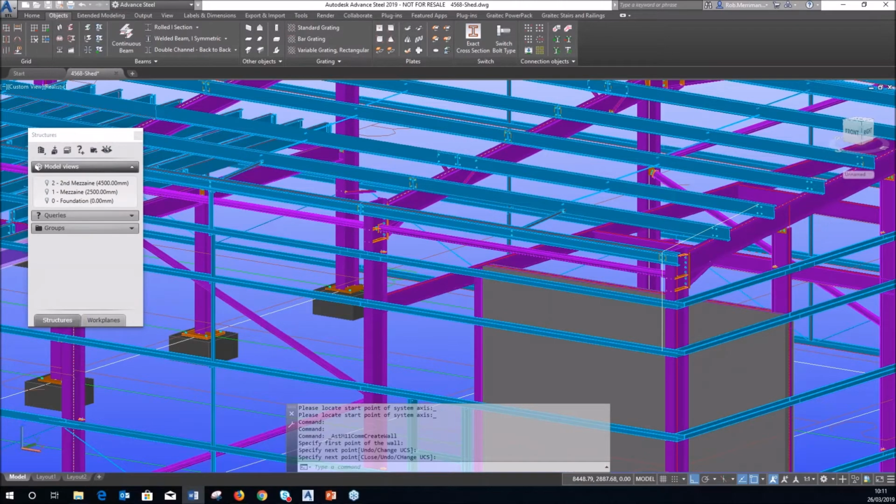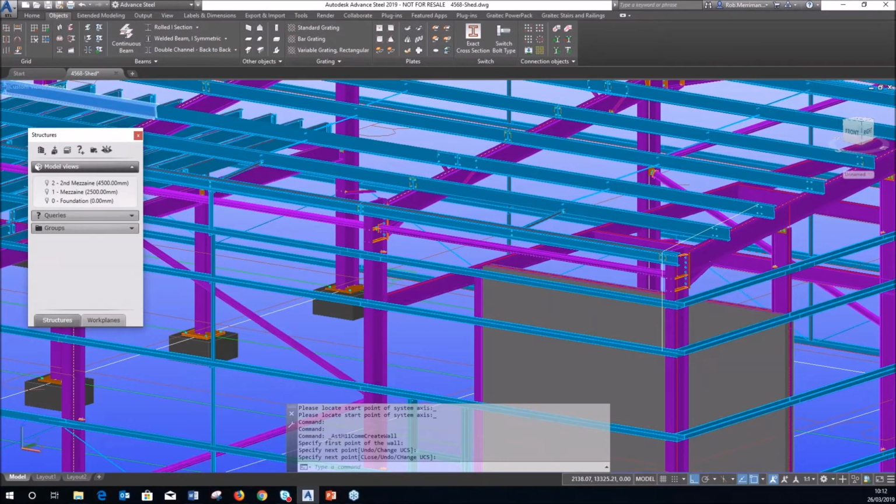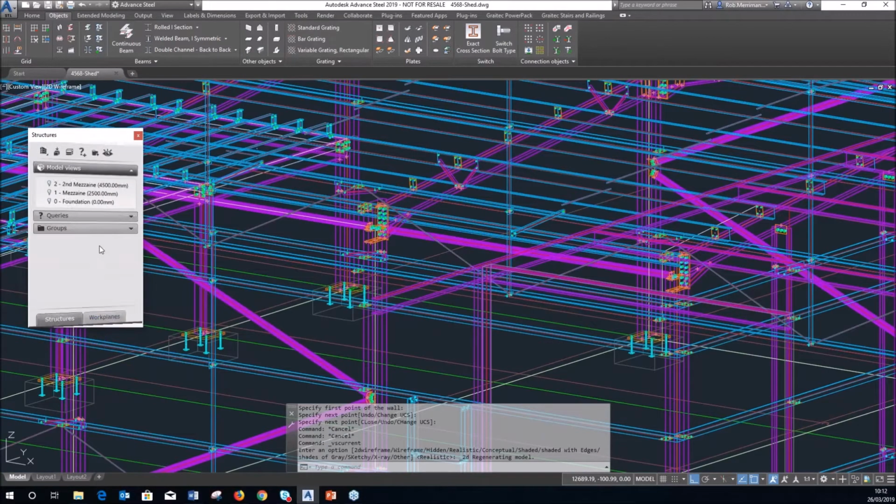Now what you can do with those levels, those work planes, is you can associate the columns and the walls to particular work planes and levels, so that as things change in the model, you don't have to manually adjust everything. Now there might be a scenario where you accidentally assign a column to a work plane, or you no longer want it associated with a work plane. So if I wanted to model a new column, I would just turn these two off, and the columns will go back to using the default 3 meters.